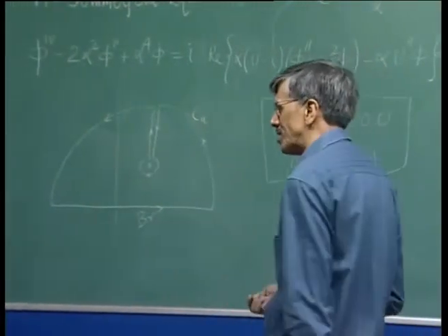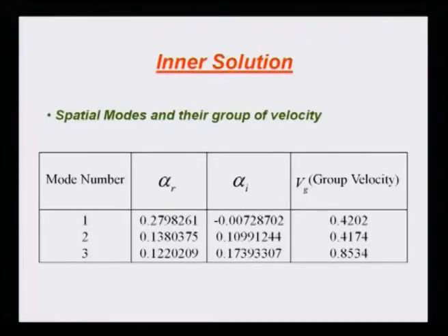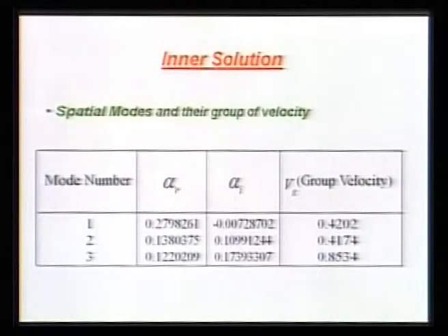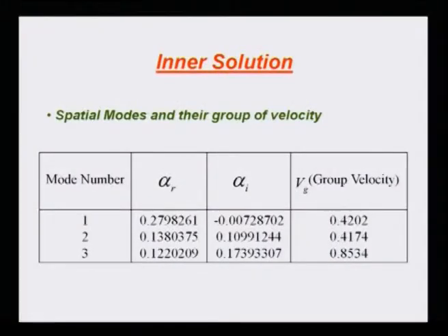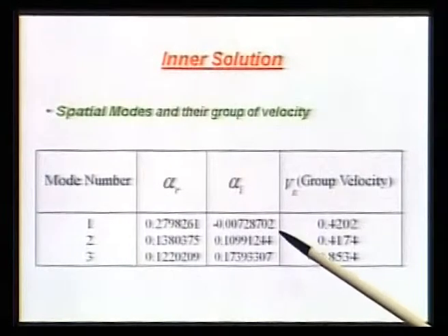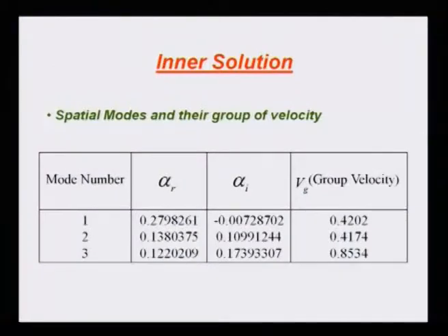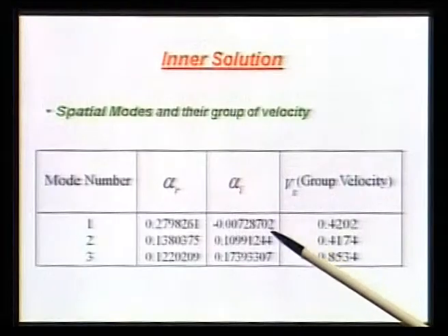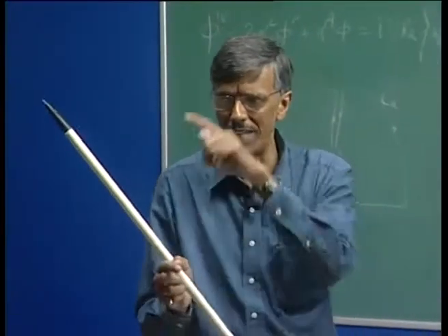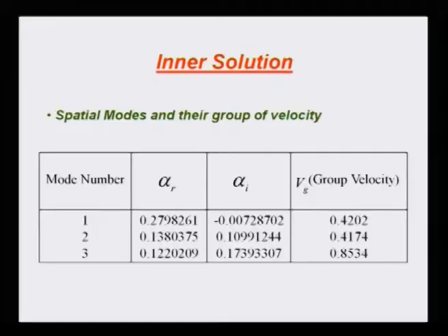This is what Tollmien and Schlichting first found out, and your eigenvalue analysis tries to obtain this. Eigenvalue analysis can also hope to find others, but to my utter amazement, about more than 2 decades ago, I found these are not very well done, and we developed the compound matrix method, and we used the grid search method, and we figured out in a box in the alpha plane, say of size 2 by 2 on all sides, and we only found these 3 eigenvalues.